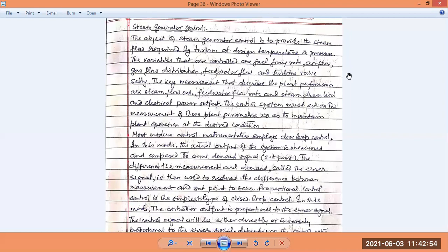Next, the steam drum load. The steam drum is possibly the heart of this type of machine, which collects the feed water. It is sent through the downcomer to the riser, where it is converted partly, to the maximum, into steam and sent to the drum again, where the heavy water falls down and the steam thus generated in the riser goes up to the superheater itself.